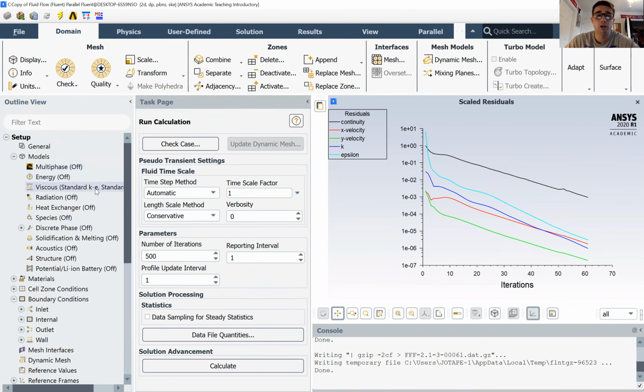In order to see our forces, we're going to go to the, where are we at here? Not the plots. We're going to go to reports. We're going to go to forces. And we're going to just select the 4 parts of the semicircle. And we're going to click print. And that is going to print all of our forces here. So we're going to minimize these components. We're going to move this up into here.